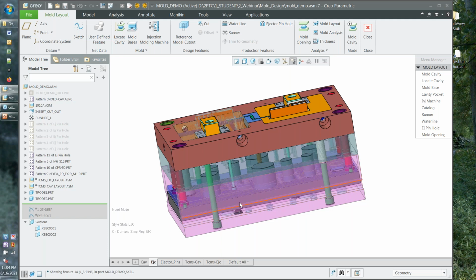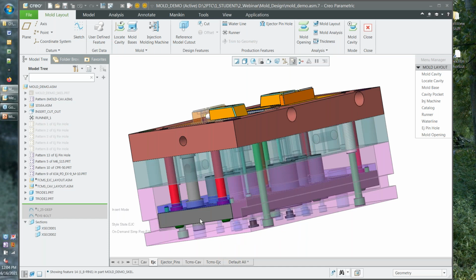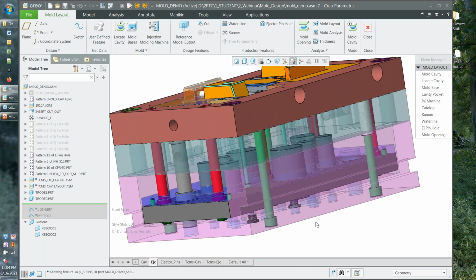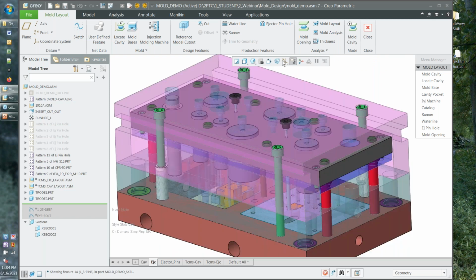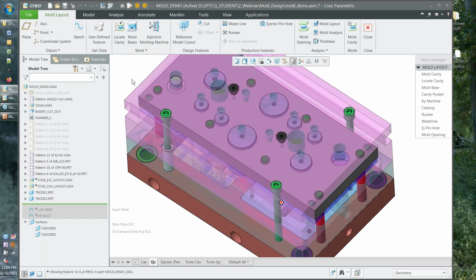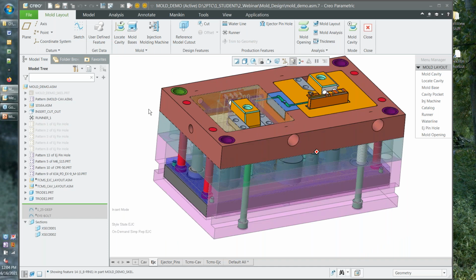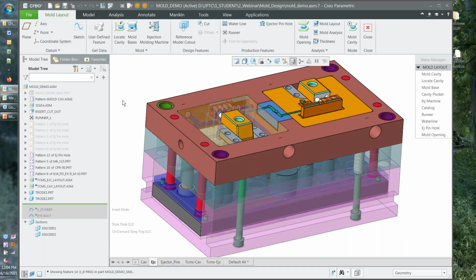We speak to support pillars. We're cutting holes for multiple components inside of the ejector house. We're bolting the thing on to the backer. It's a lot of things that are interacting with each other, and managing these objects through a skeleton model does in fact make an enormous amount of sense to really keep things clean and optimize your tool design.